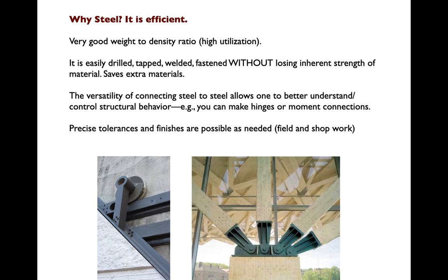On the right, you see a typical set of hinge connections where steel has been formed into elements that take and collect the load from these timber struts. They bring them down onto connections that allow the struts to rotate so that the roof of the structure can move around a little bit without twisting the foundation basically out of the ground, without transmitting the bending forces from one element to the other.